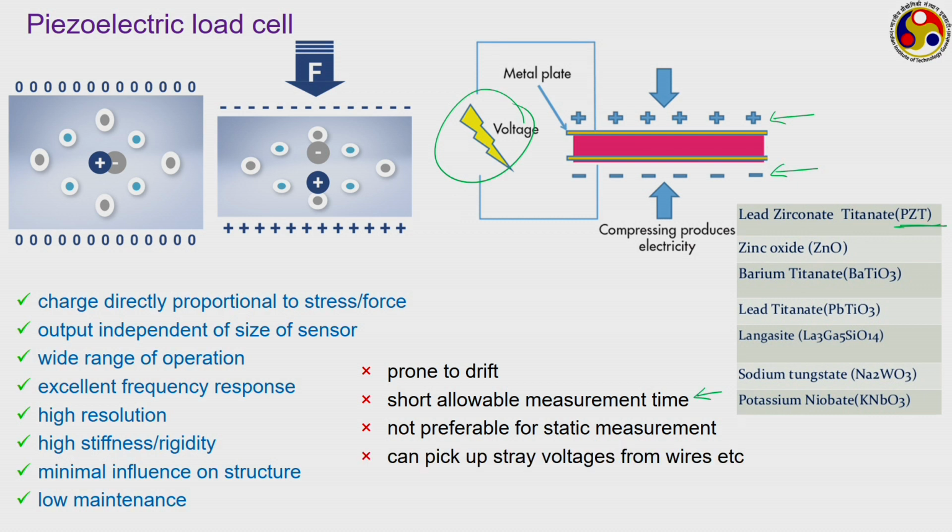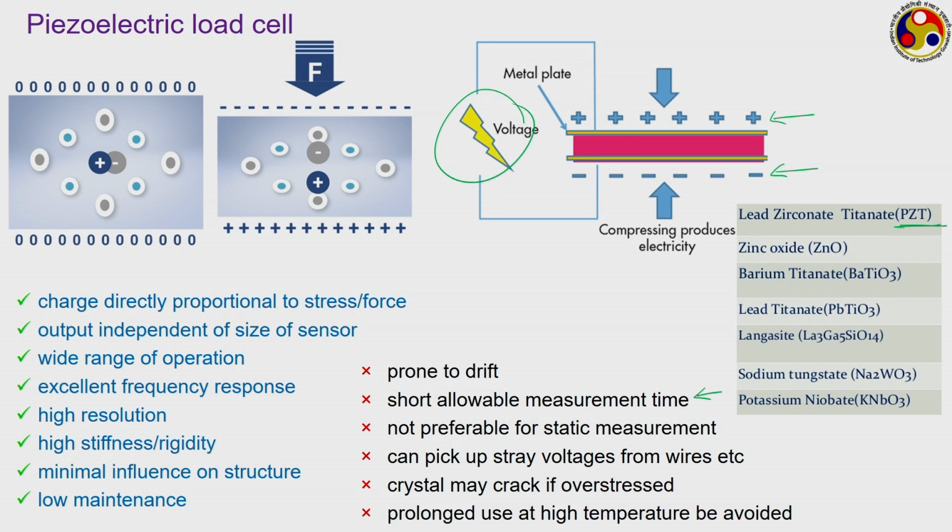Another issue can be that it can pick up stray voltages from the wires, and it will be very difficult to separate that out from the final output, because at the output level there is no difference. The crystals may also be quite delicate, so if they are subjected to overpressure they may crack or deform, and prolonged use at high temperature must be avoided, because they may show some kind of mechanical deformation when subjected to high temperatures for a long duration of time. Despite these problems, piezoelectric load cells are here to stay, and they are probably the most suitable device among all the ones that we have discussed so far for dynamic force measurement.